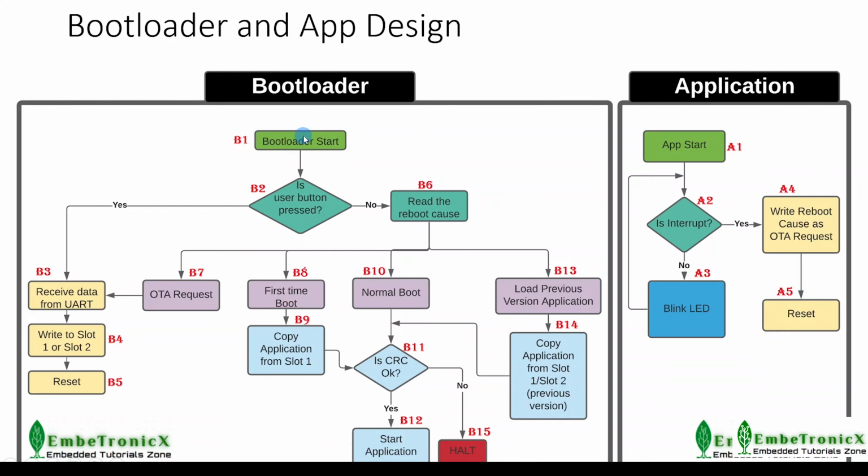So again the bootloader starts and checks the GPIO state. Now, as the firmware has been updated, the GPIO will be high. So it will go here.